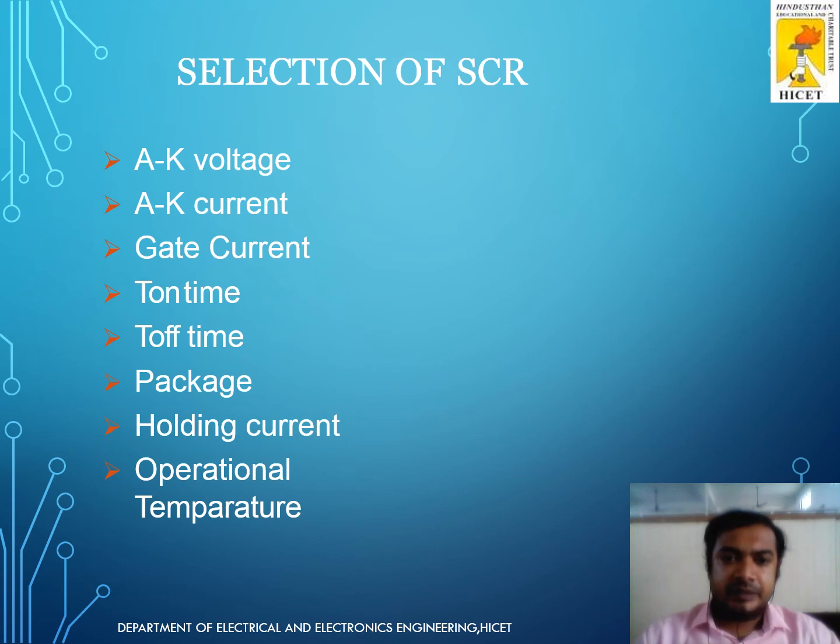Selection of SCR. An SCR can be selected on the basis of anode to cathode voltage, anode to cathode current, gate current, turn on time, turn off time, package, holding current, and operational temperature.